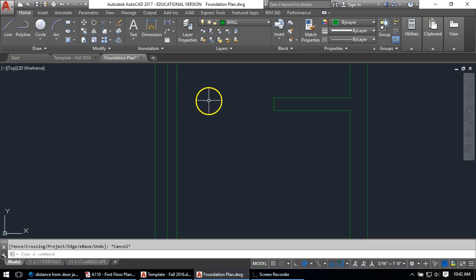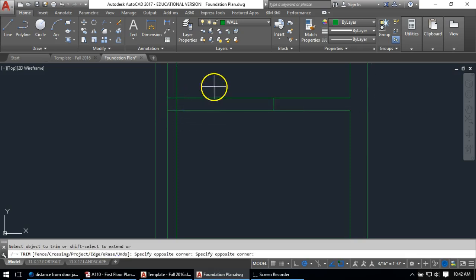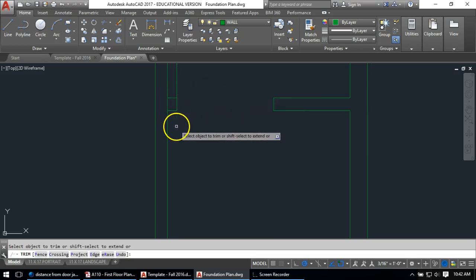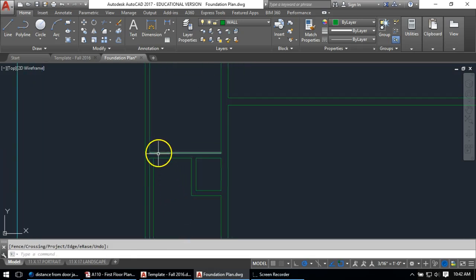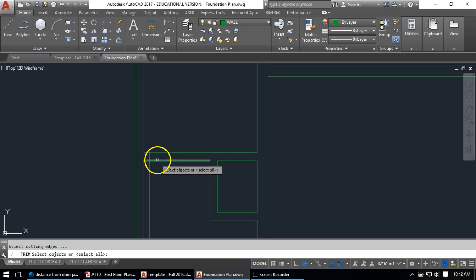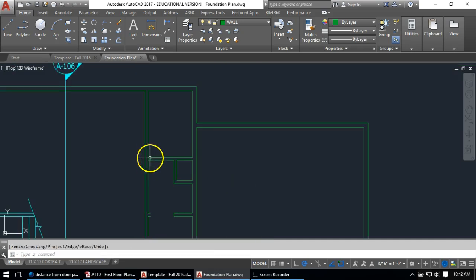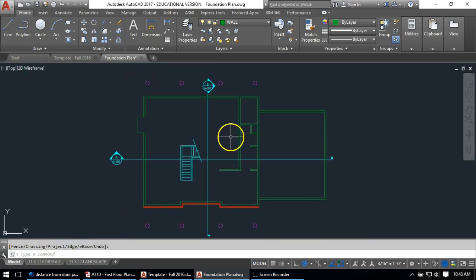thing happening on this side right here. They got a little wall to make it like a little opening here. So I'm just going to pull those lines over, trim that up to get that effect. And then I will just say, I'm just going to put this wall here for now. I'm not doing doors really yet, but since it's all in alignment, my door is going to start there and come over. So I'll just mark that point at this point in time and keep going on with my walls.